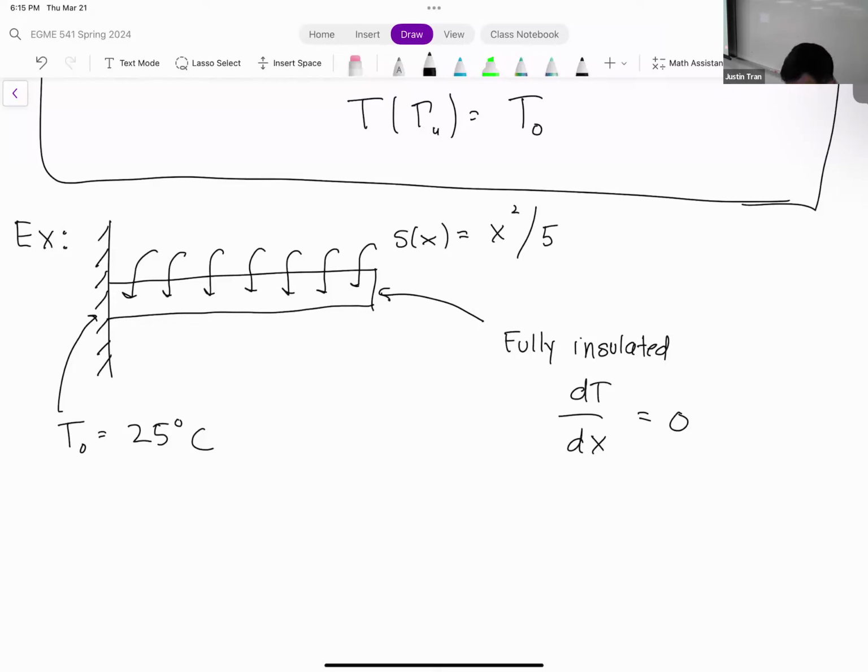Can you explain what thermal generation is? Yes. Thermal generation represents the ability of a material, by itself, to generate heat on its own. Most often this occurs where you have a very thin electric heater, sometimes sandwiched in between two different types of materials. That heater will be generating heat just through electricity, and so when you're solving for the temperature in that entire solid, that thermal generation needs to be taken into account.